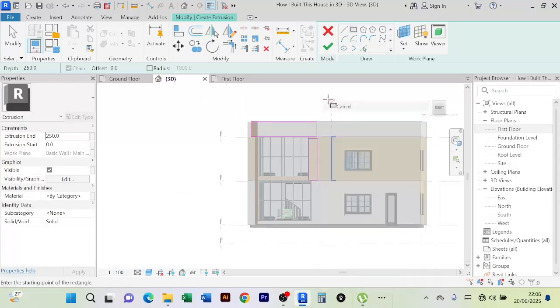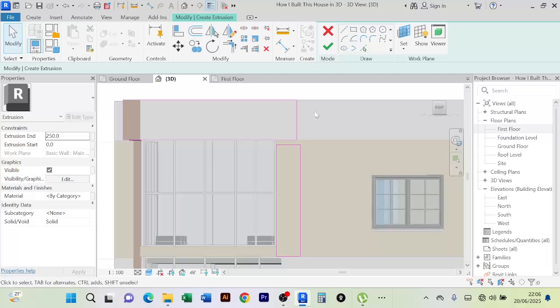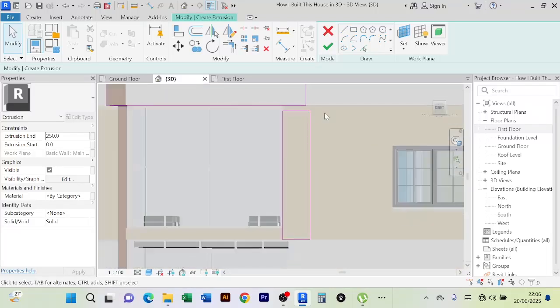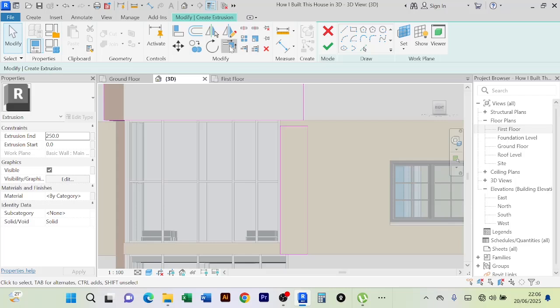Then of course we know what we're supposed to do. We're going to extend this. So what I want to do, I'll come to my trim, I'll extend this to that one. Then of course I'll delete this one here. And then I'm going to split with the split tool. I'll split here. I'll come to the trim. I'll trim this to that, just like that. I'll delete this excess,